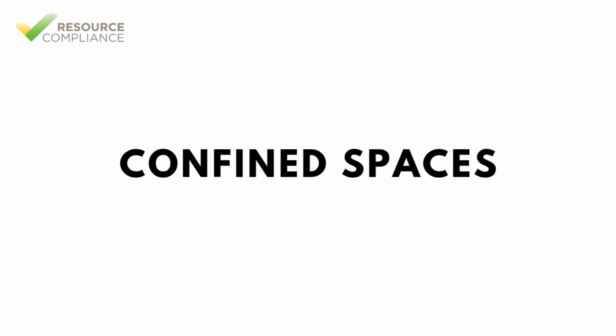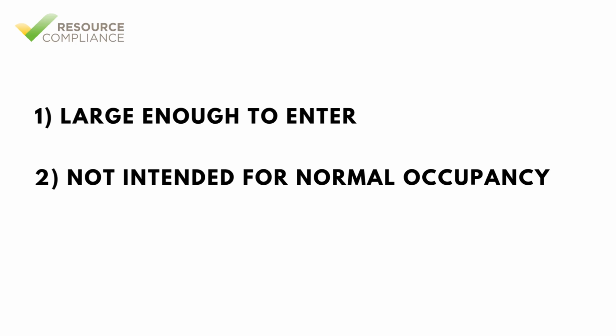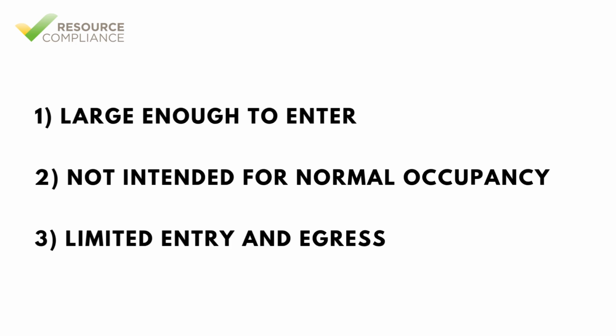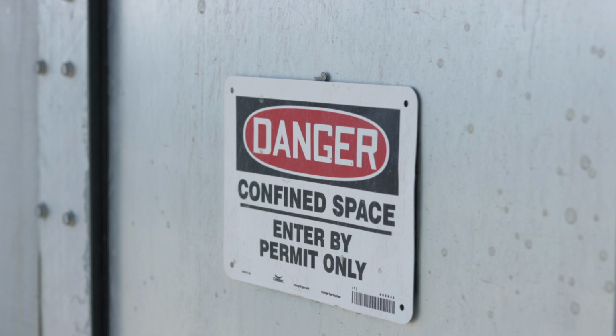A confined space is any area that is large enough to enter, is not designed for continuous occupancy, and has limited openings for entry or exit. Some confined spaces may be classified as permit required if any of the following are true.